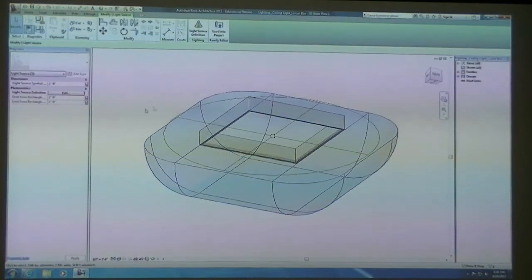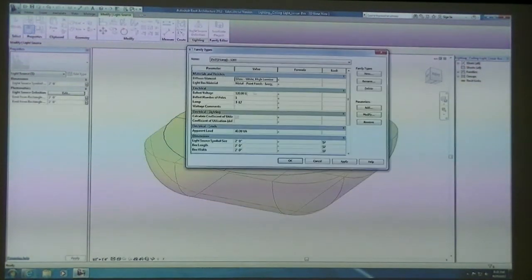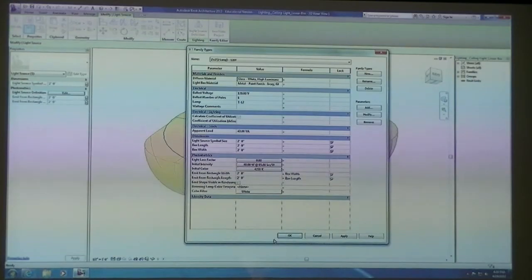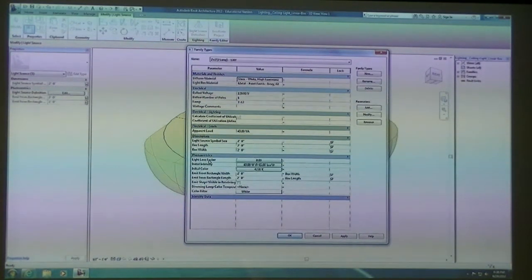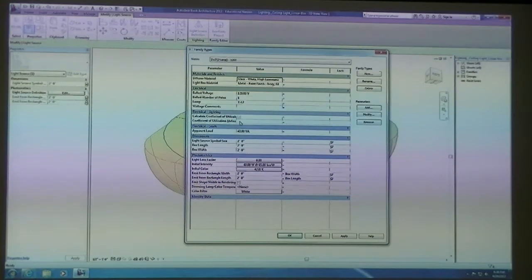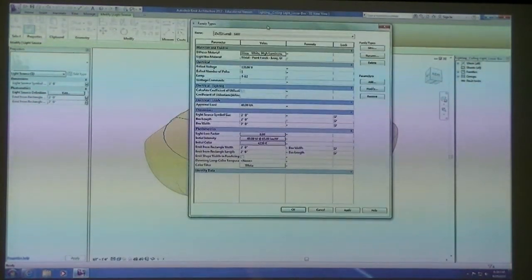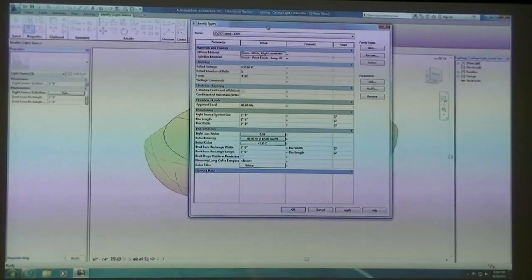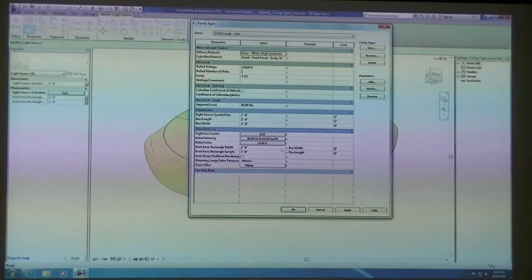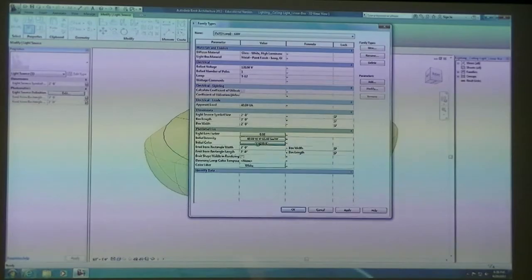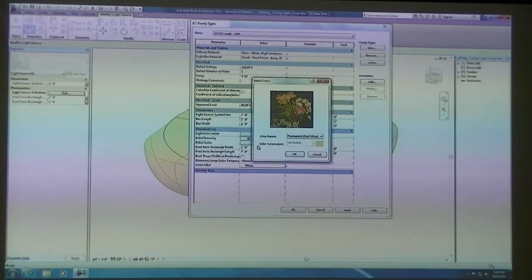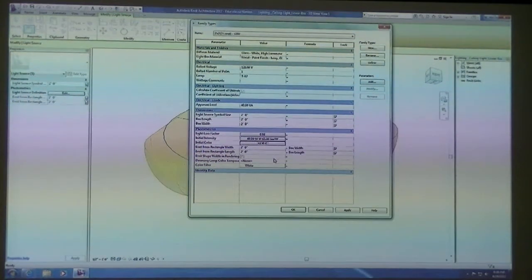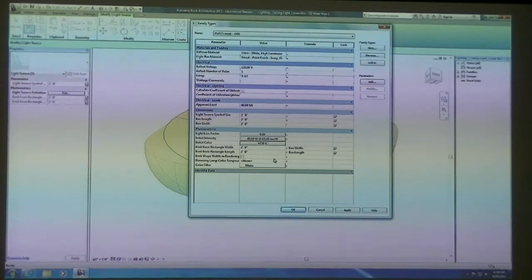And then if you remember, each light comes with its own set of properties associated with the photometrics of the light. We didn't go into all of the different settings that you can do, because most of the lights that you can get from Revit or from a lighting manufacturer, when you download their actual models, already come with the appropriate light loss factor, the initial intensity, the initial color in kelvins, and all these different things that the lighting manufacturer would know better.